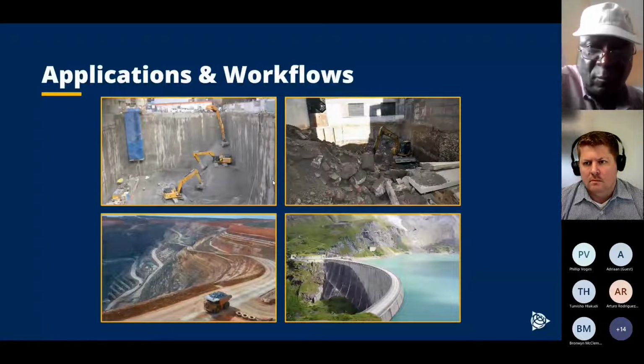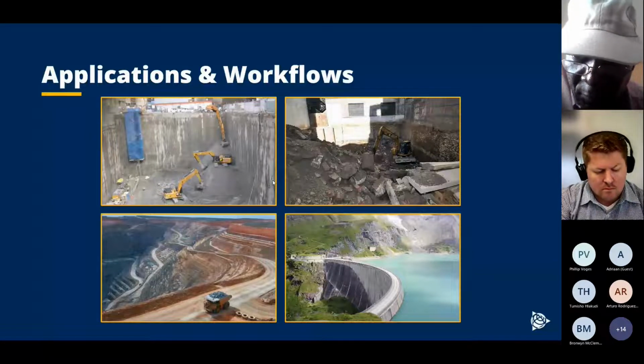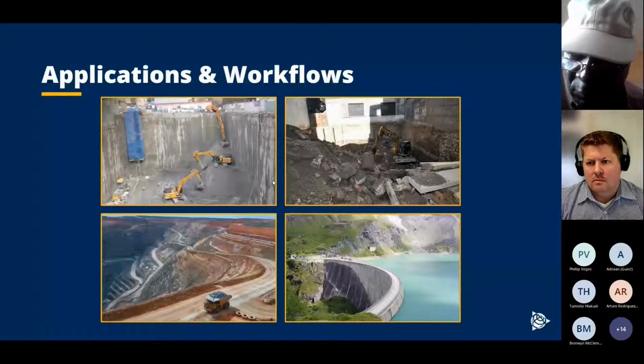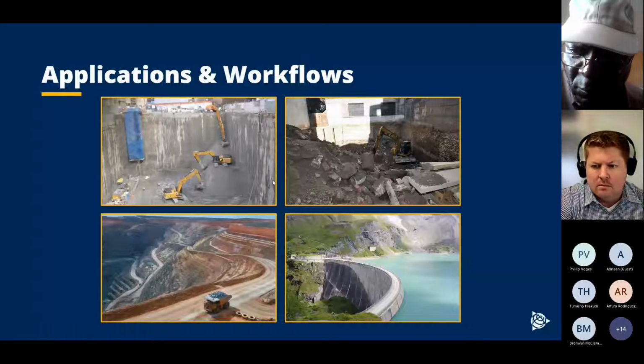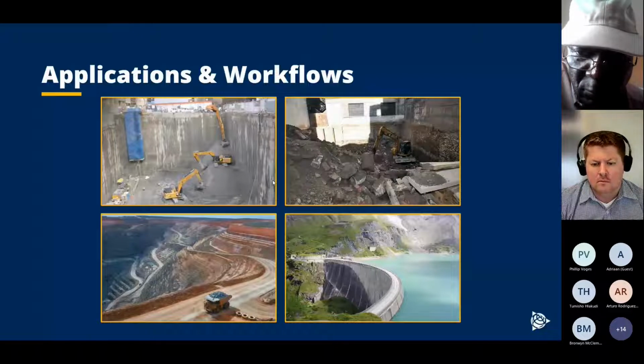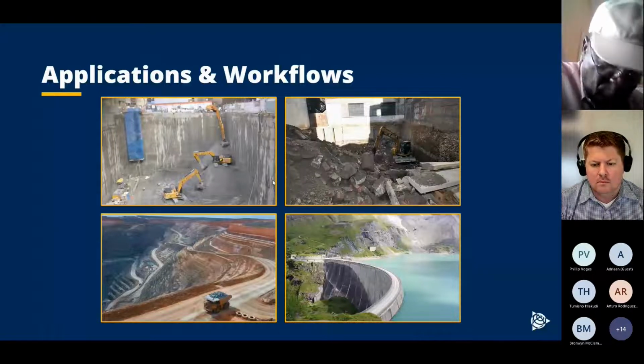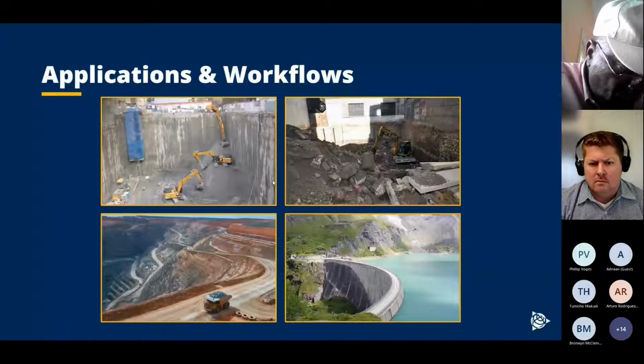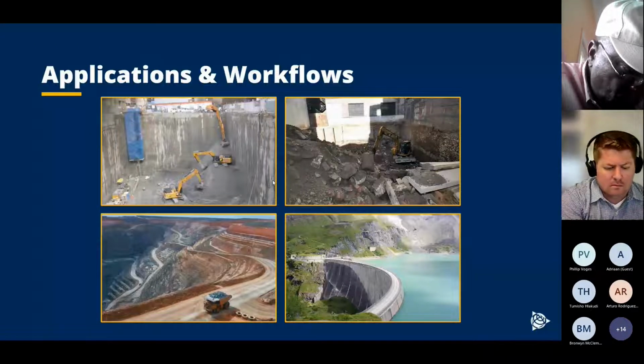The typical application there is to monitor these sheet piles during the time of the excavation. This does not necessarily need to be automated. This can be done manually or by campaigns. So you can imagine going there, setting up your instrument and monitoring several points at the sheet piles and maybe the buildings around during the time of working.